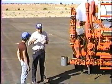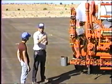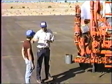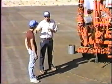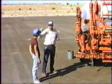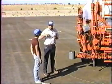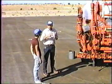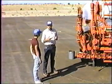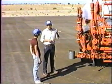And if you put 0.40 gallon per square yard on all of those pads, they're going to be smiling from ear to ear. If you put 0.2 on some of the pads and 0.6 on other pads, they're going to tell you to go home. Or they may give you one more opportunity to make some adjustments on the truck and pass that test. It's called the transverse spread test. On the second test, if you don't pass it, they're going to run you off.